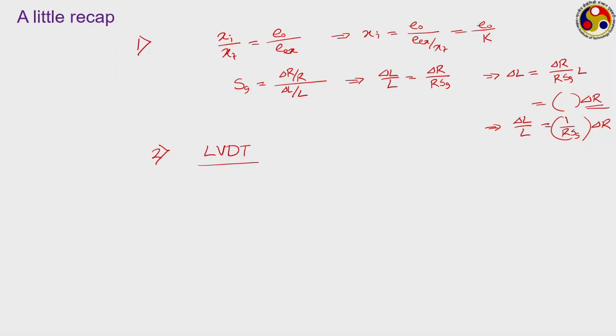The other one is the inductosyn, which is also a very popular one and quite easy to use. Then we have also discussed the capacitive instrument, the optical group of methods and also the ultrasonic group of methods. All are quite common, but still generally the LVDT, potentiometer and strain gauges are the most common three instruments which are used for displacement measurement.